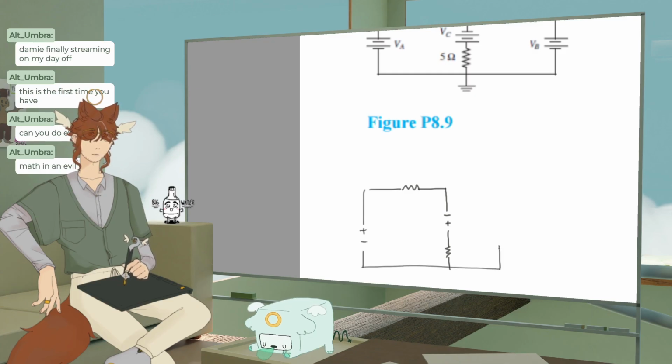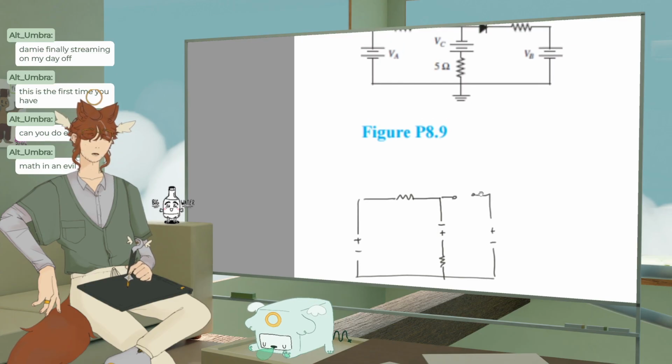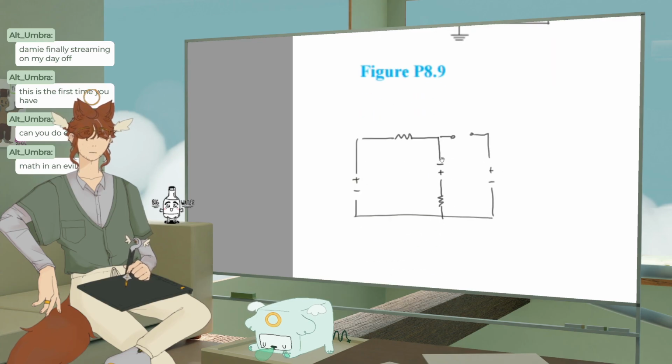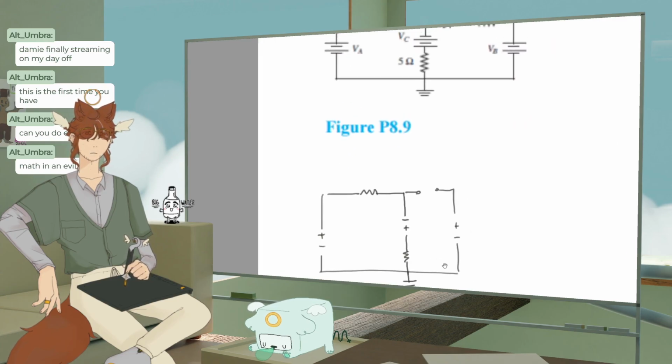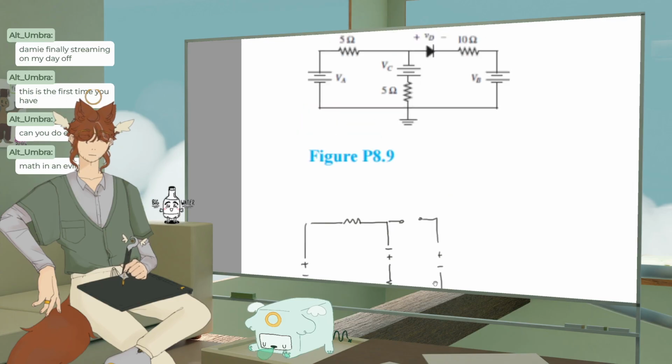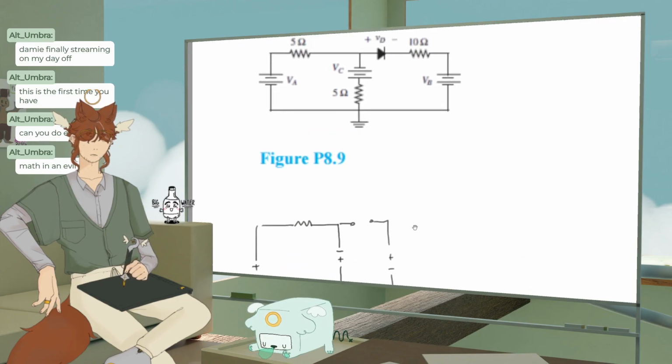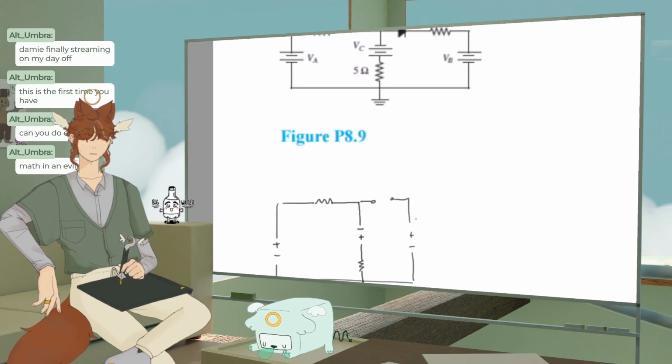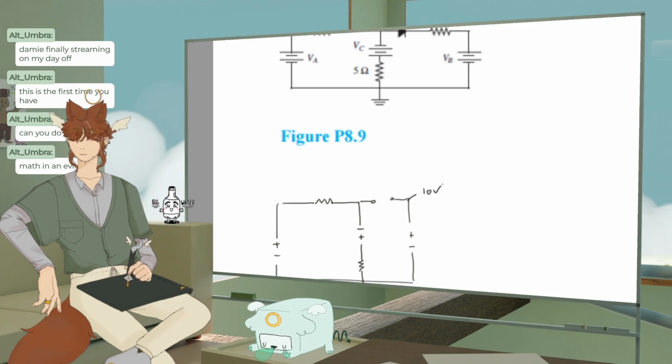So we're going to take out the diode. That was the first thing. I actually did that right, and I was like, oh, okay, cool. So diode removed. We want to find the voltage here and the voltage here, so this is ground. VB equals 10. So right now the voltage here is 10 volts, because this is 0 volts. So we just need to find the voltage here, which is the same as finding the voltage here. So to find this voltage...